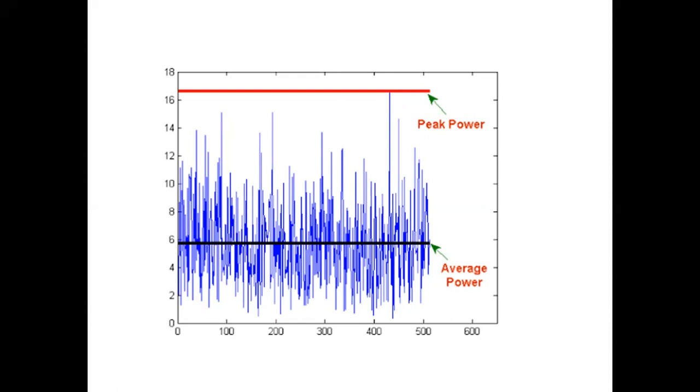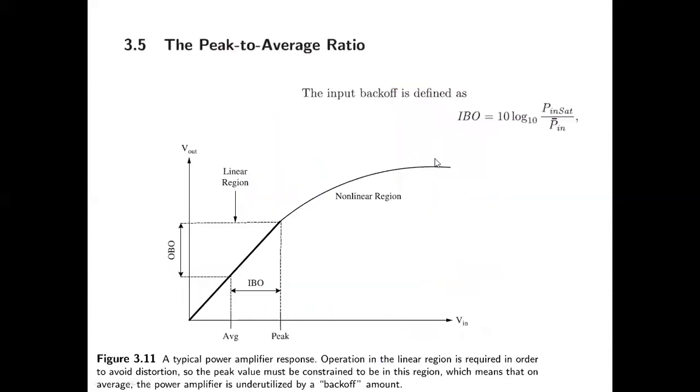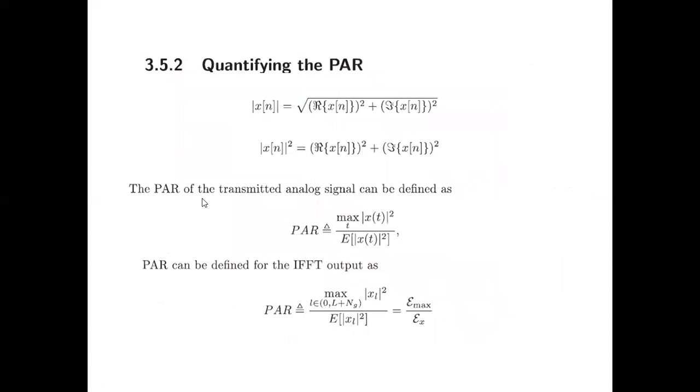In this particular case, say all the data is a constant. Say I take the value 11111111 and I take an 8-point DFT. What is the answer? The 8-point DFT of 11111111 is 8 delta. That means it's a sudden spike. So even though your time domain data has a very low peak to average power ratio, did you get the value? By the way, what is peak to average power ratio? Peak to average power ratio is maximum power divided by average power.